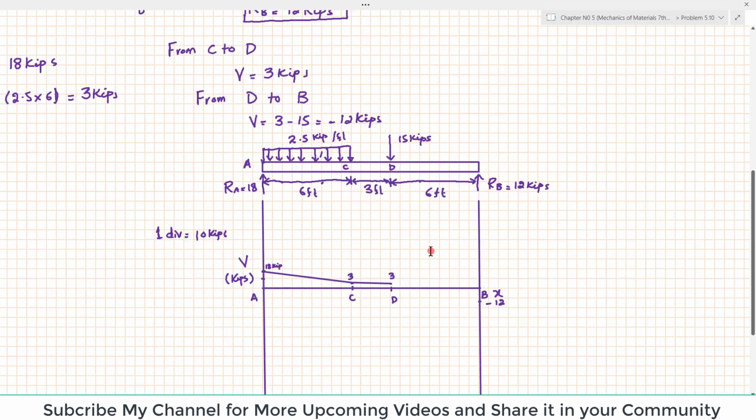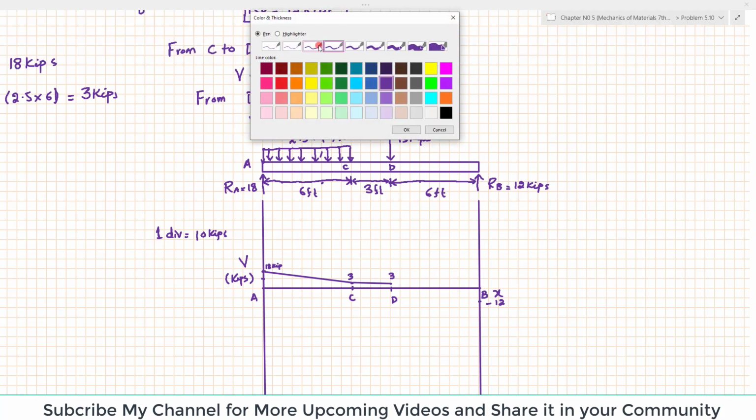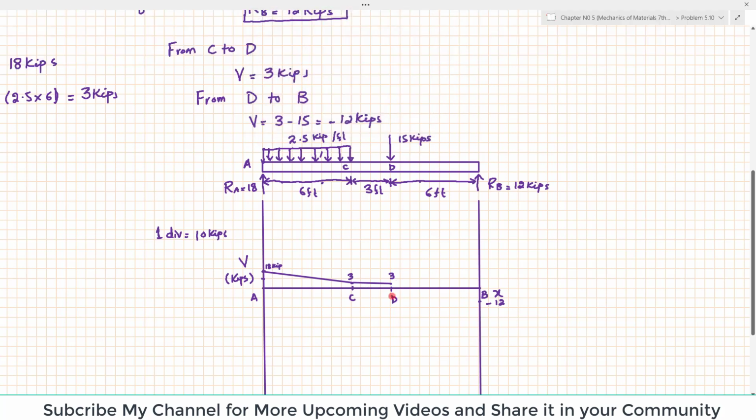Now from D to B, you can see the load is minus 12 kips. So I will draw a vertical line that will go to minus 12. So this is 10 and this will be minus 12. And this line will go straight because there is no other load between D and B, and at B this load is 12. So minus 12 plus 12 will become 0. Let me clear it.